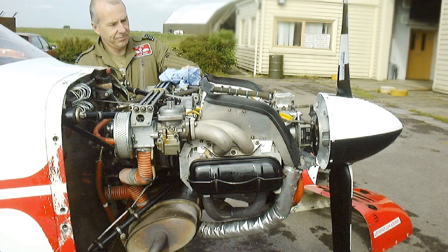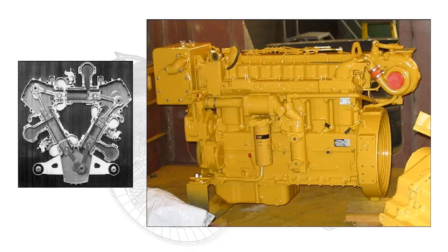Lighter loaded engines use a low viscosity or thin oil, whereas higher powered engines with higher loading would require a high viscosity or thick oil. As previously stated, the air temperature in which the engine operates also has an influence on the viscosity of the oil selected for use in that engine. For example, a light aircraft operating within the United Kingdom during the winter may use an 80 grade oil, and in summer it would use a 100 grade, the choice of the grade being dependent on the average ambient temperature.